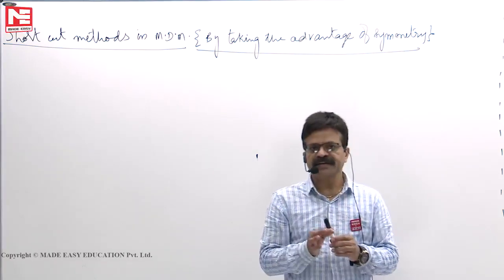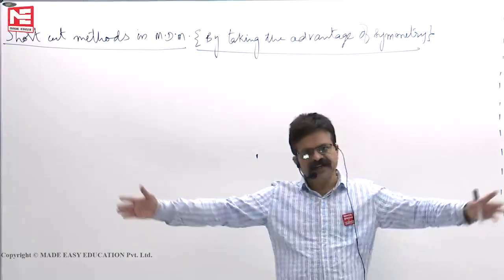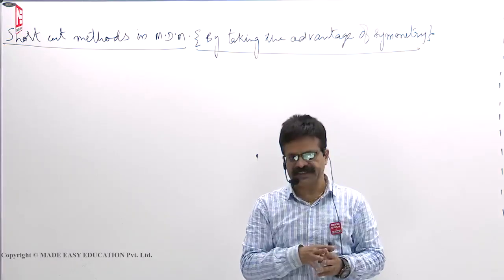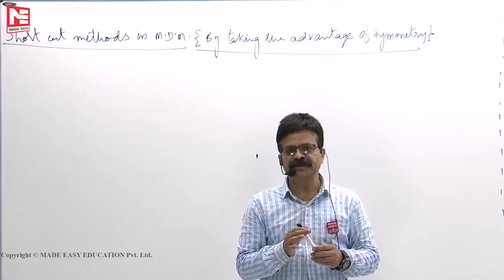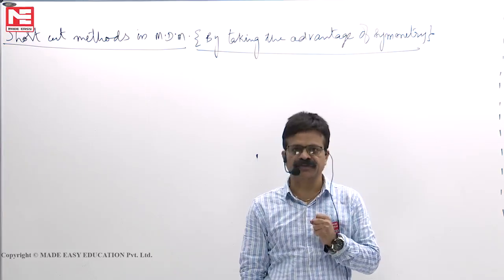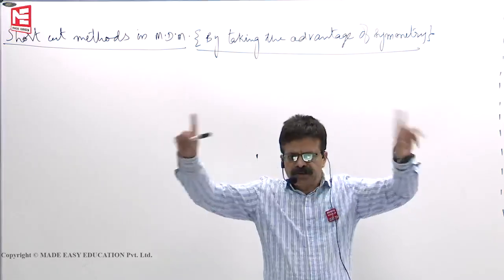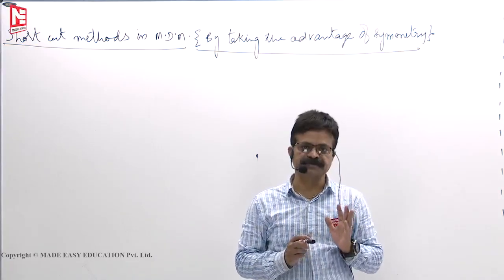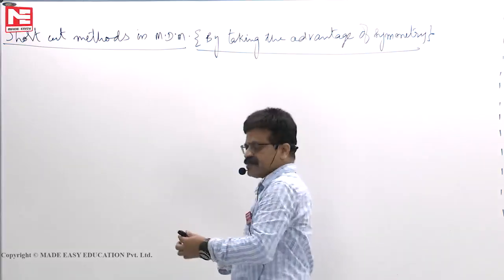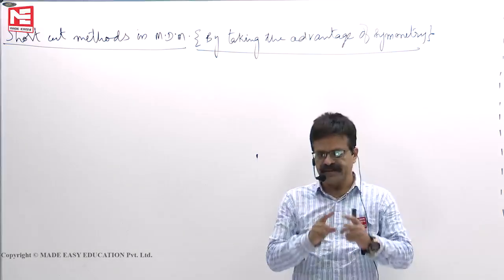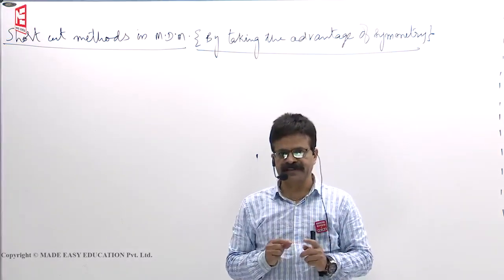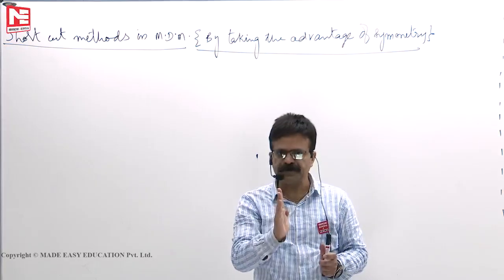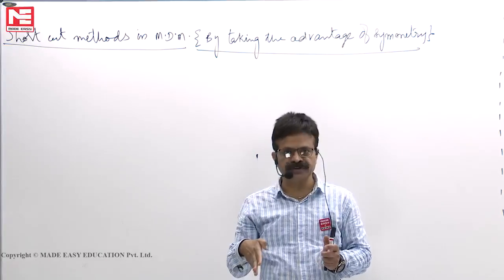So in the process, instead of solving the entire frame or beam and wasting our time, we take only half of the structure and complete the problem in our specified 30 or 40 seconds time. Initially it looks like so big a problem, but we still can complete it in 40 seconds maximum. Okay, so we'll take first, two possibilities can exist. If you have a continuous beam or frame, the axis of symmetry can pass through the midspan or it can pass through the support.